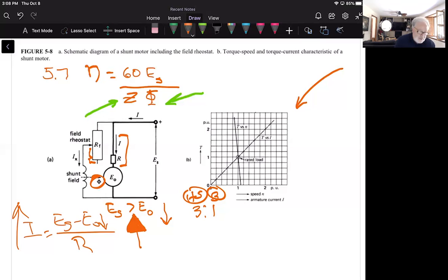Now there is a certain thing, and I'll try to demonstrate this in the lab to you, that under abnormal conditions the flux may drop out. For example, maybe the excitation current of a motor is interrupted accidentally, and the only flux that would be left would be this remnant magnetism in the poles.